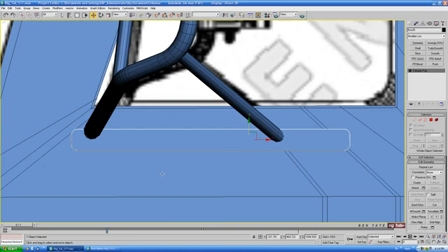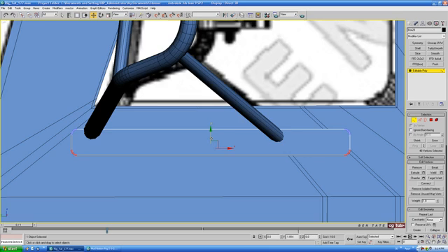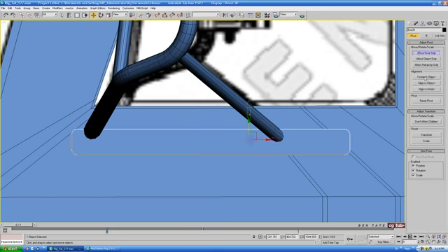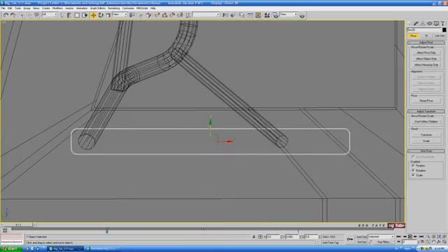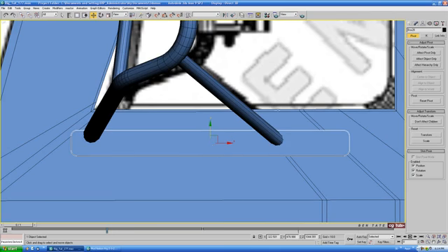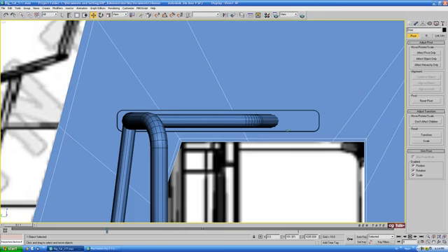And I think we might need to make it a little bit thicker top to bottom, so let's go back into vertex here. Let's get on a wireframe with F3. Okay, we'll grab all the bottom verts here and just make it a little bit thicker. Maybe something like that. Okay, let's also maybe center the pivot point here, so I'm just going to go in the hierarchy tab, affect pivot only, and center to object, and turn the button off. Okay, I'll just kind of adjust this here a bit. And maybe for the top one, we'll thicken that up a little bit as well.